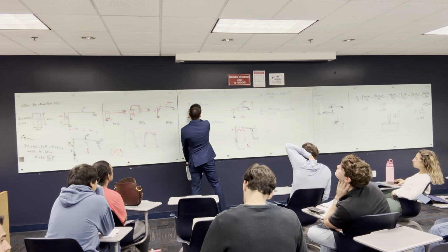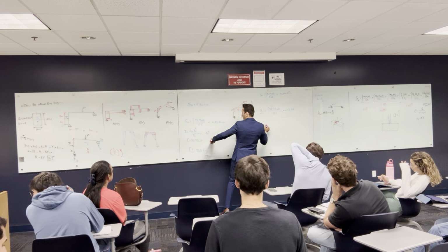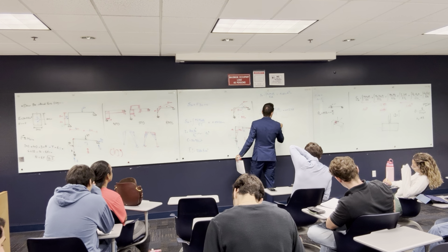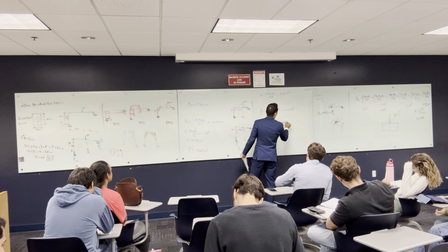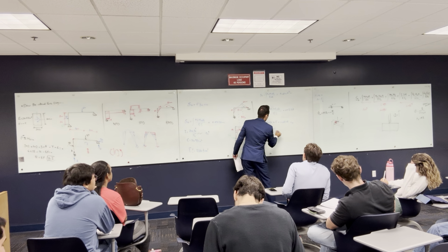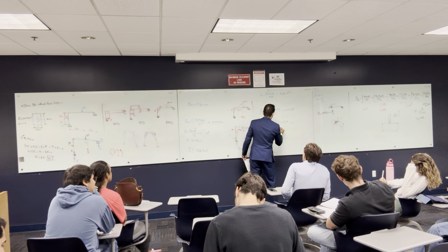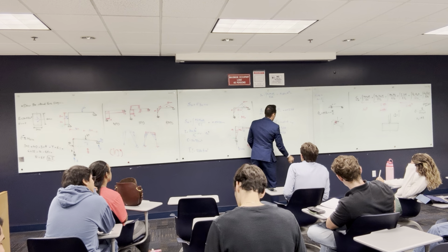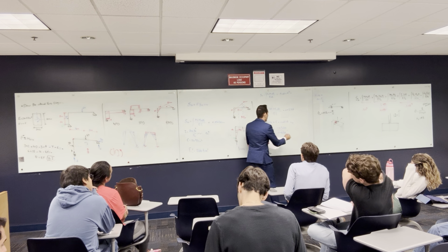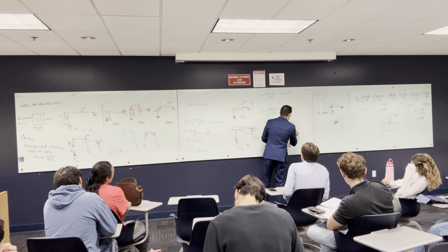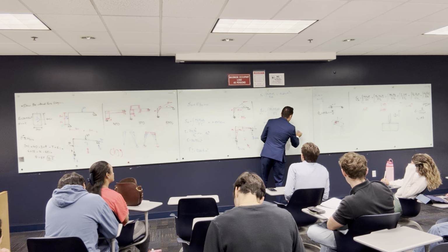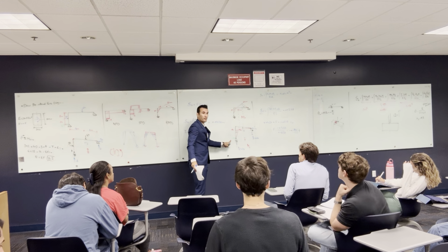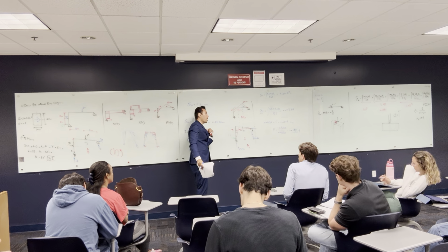All right, so right now I have delta 10 and delta 11, so I can put them here. 0.01026 plus F multiplied by 0.0234 equal to 0. So F is going to be equal to negative 0.01026 over 0.0234. This is going to give us F equal to negative 0.452. What does the negative mean? That means that I assumed the unit load 1 in the opposite direction, so the reaction should be in the other way.